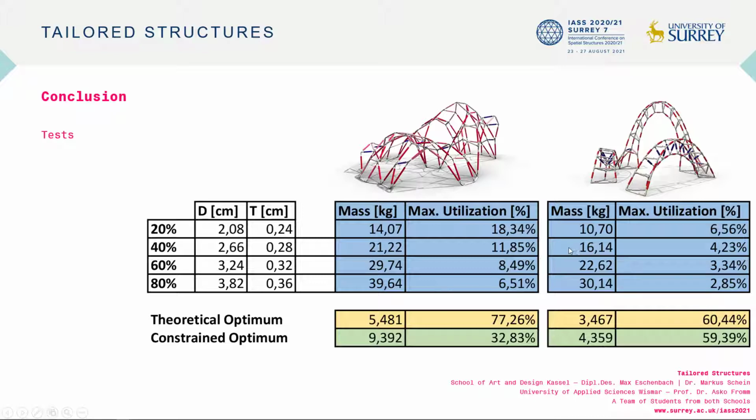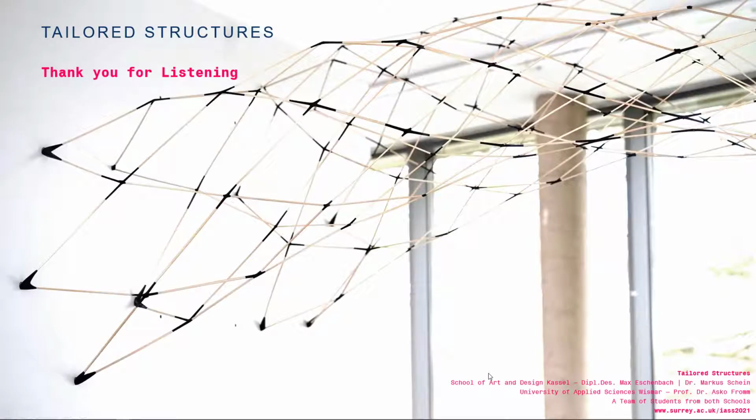And after member assignment, things should become worse again, as not all optimal member cross-sections may exist in the required number or required length in the library, and this behavior happened as well as expected, but still the resulting mass was less than the benchmark calculations. This was our Tailored Structures approach.